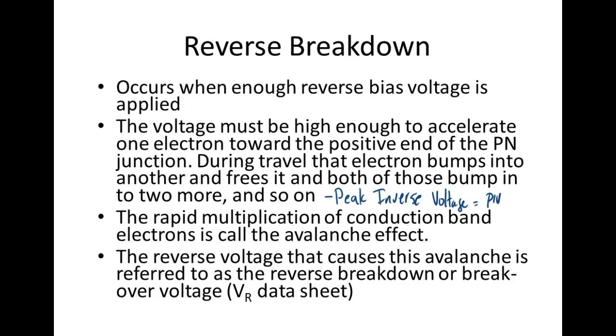If diodes get hot, yeah, they do get hot. They drop a voltage even before the reverse bias direction, right? This little 1 amp diode drops about 700 millivolts, so that's about 0.7 watt.